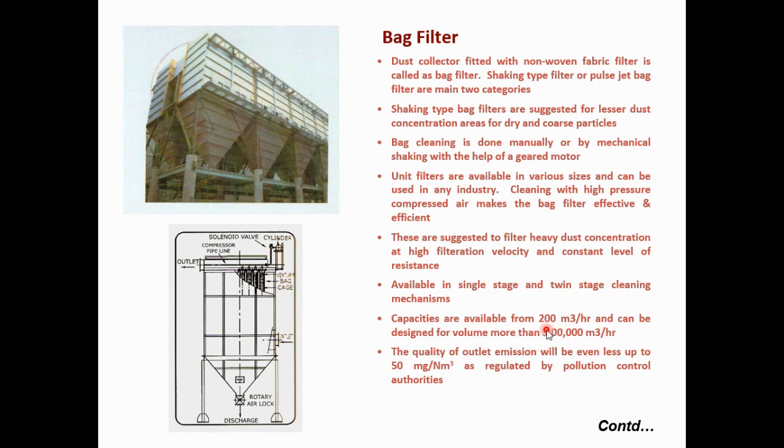Capacity is available from 200 meter cube per hour to more than 300 thousand meter cube per hour. Depending on the size, we have to design the bag filter according to your requirement. The quantity of the outlet emission can be even less, up to 50 milligram per meter cube, as regulated by the Pollution Control Board.